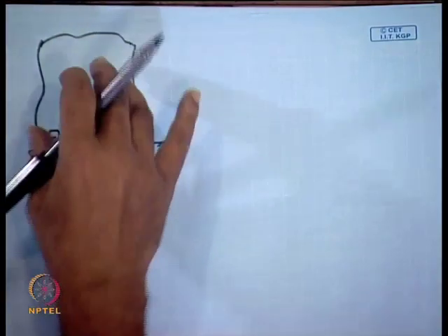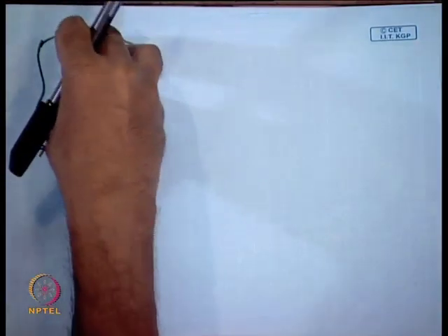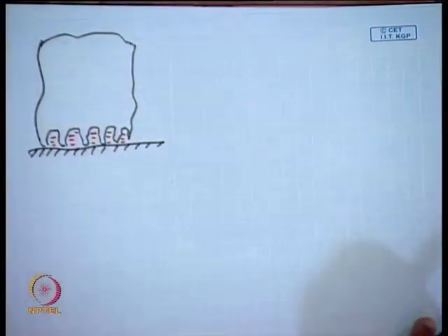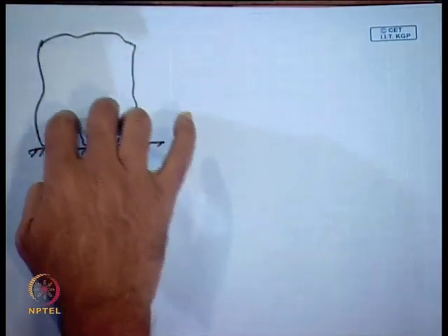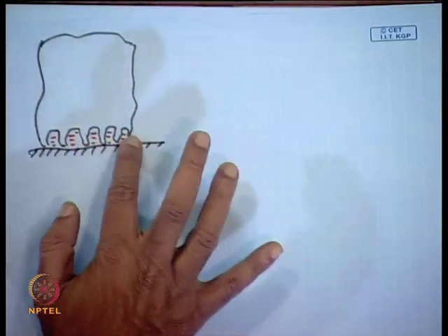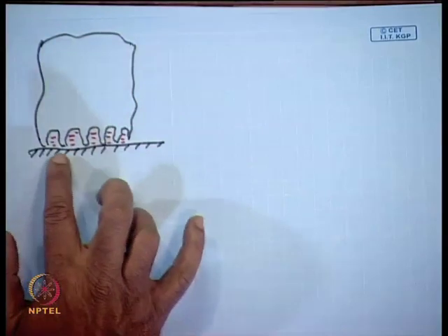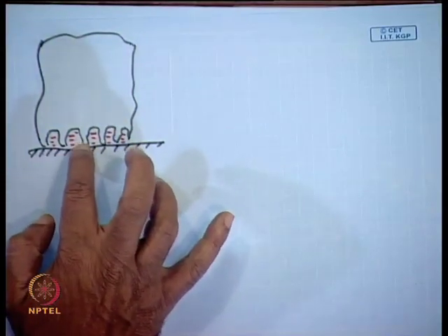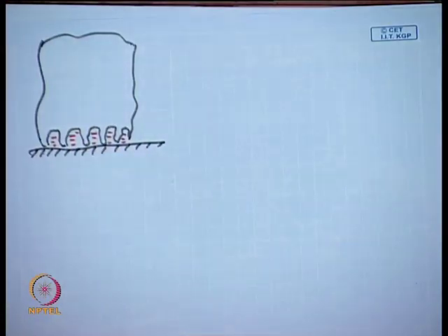Now, before it reaches the critical mass for leaving the surface, if the liquid shown over here by this red dot dries up, then what will happen? A vapor patch will form. Suppose in this way this vapor slug leaves, another vapor slug grows, then there is no dry patch. There are a number of vapor stems, that is true, but even then the surface has some contact with liquid.